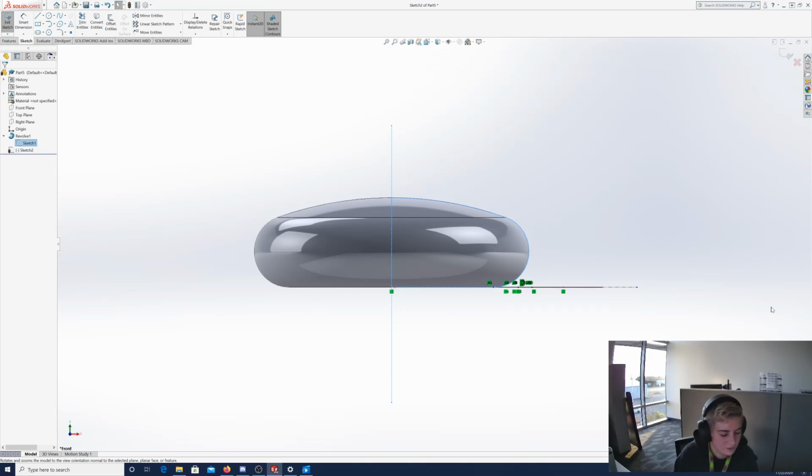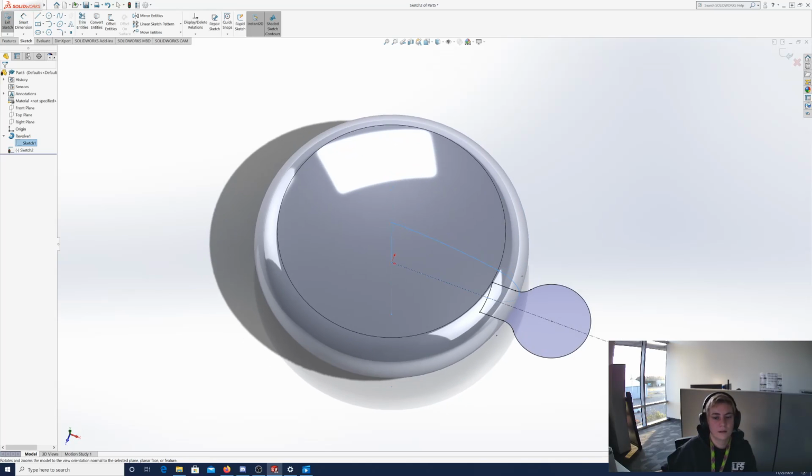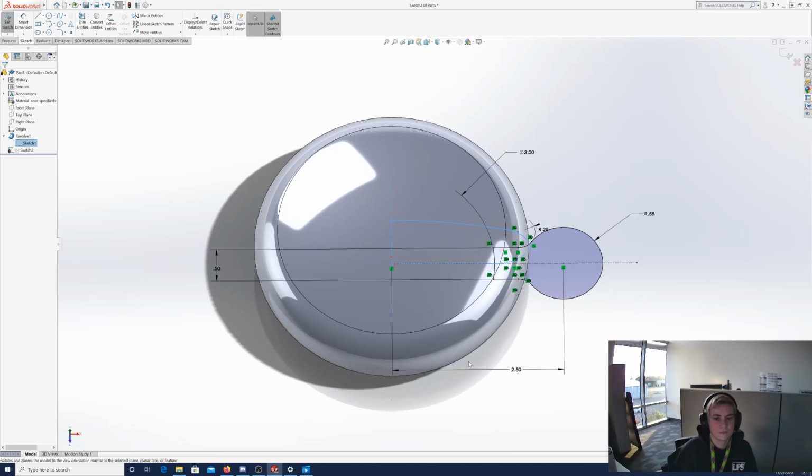If you did the first sketch and then the revolve correctly, it should end up like that. So, alright. If everybody's got that, does anyone not have that? Is anyone not with me? The lines and the arcs leading to my circle are underdefined.